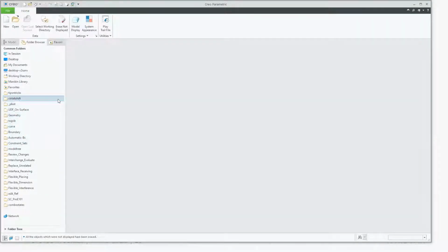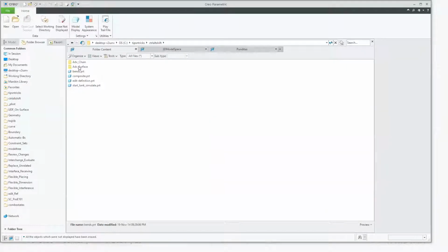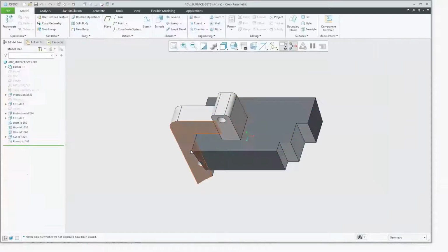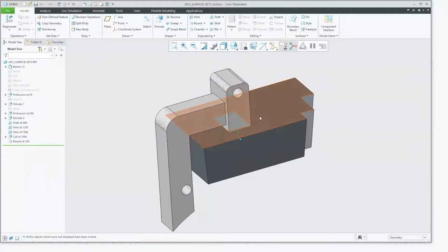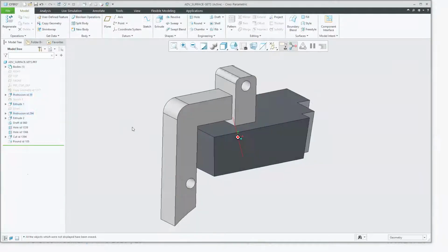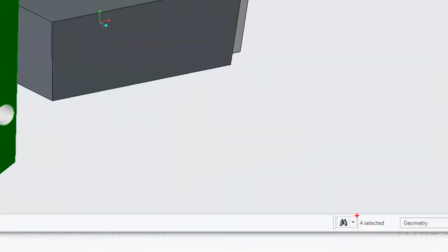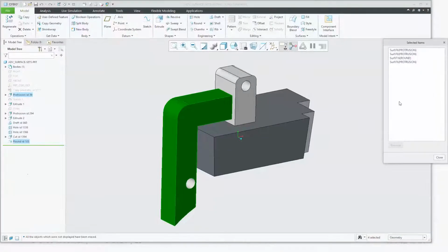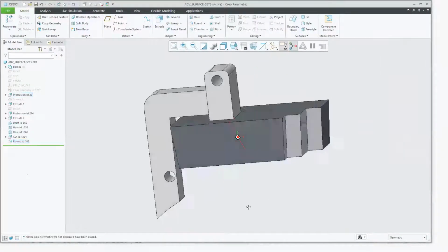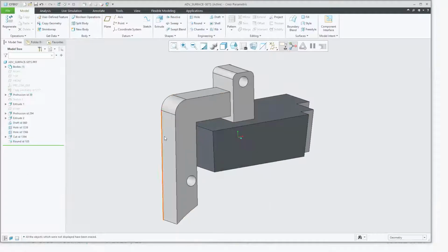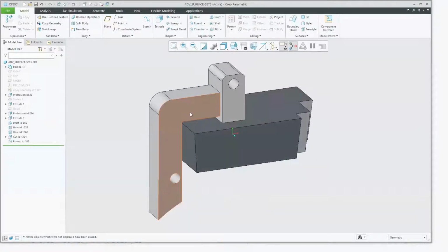I'm going to go over a few more in here, mainly for surface selection, right? Sometimes in surface selection, for example, if I go open up a different design here. As I'm selecting, I know that I can hold control and I can just select surfaces, right? It's easy to select surfaces. I know it's not too complex, so I can hold control key and I've grabbed about 4 items here, as you can see, right? If I double click on that, it's 4 selected. But is there a quick way to select all items based on a rule, like we call it seed and boundary, anchor boundary, seed and boundary? That might be very, very handy, right?